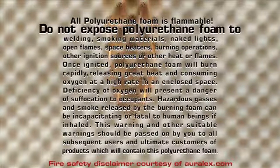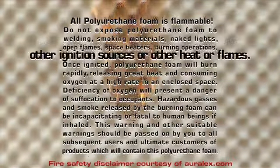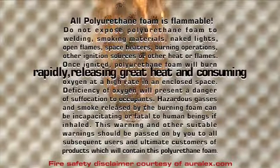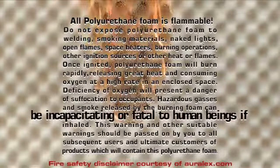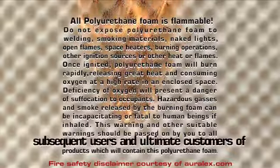Do not expose polyurethane foam to welding, smoking materials, naked lights, open flames, space heaters, burning operations, other ignition sources, or heat or other flames. Once ignited, polyurethane foam will burn rapidly, releasing great heat and consuming oxygen at a high rate in an enclosed space. Deficiency of oxygen will present a danger of suffocation to occupants. Hazardous gases and smoke released by the burning foam can be incapacitating or fatal to human beings if inhaled. This warning and all other suitable warnings should be passed on by you to all subsequent users and ultimate customers of products which contain this polyurethane foam.